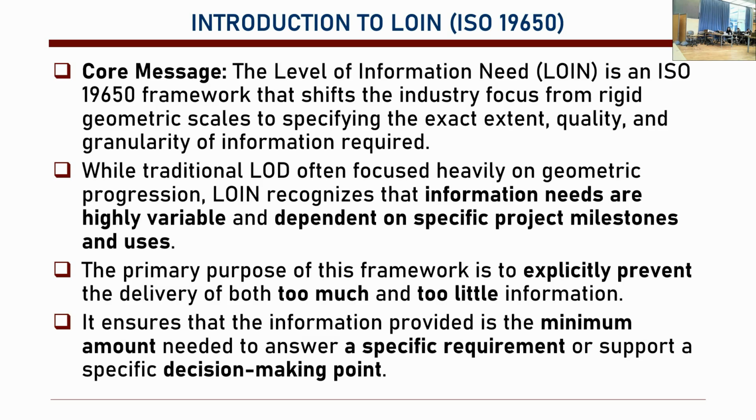I mean, how can I say? For instance, you're a structural engineer, okay? An architect's design is still in LOD 200, but you are putting very highly detailed columns into the model directly, okay? So that is not what we want. If they do that, the whole thing becomes complicated. So we don't want to do that.